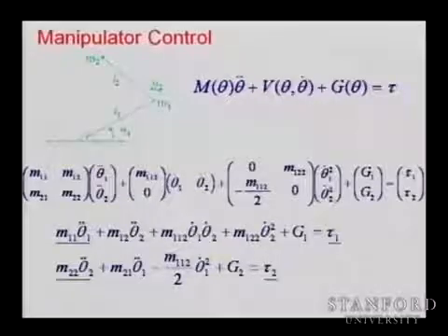As you accelerate, you have a coupling through M12, and that is producing disturbance forces or inertial forces on the first joint. We have opposing forces coming from the acceleration of joint 1 on joint 2.